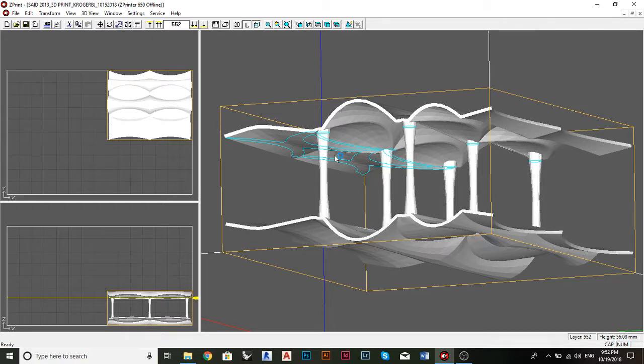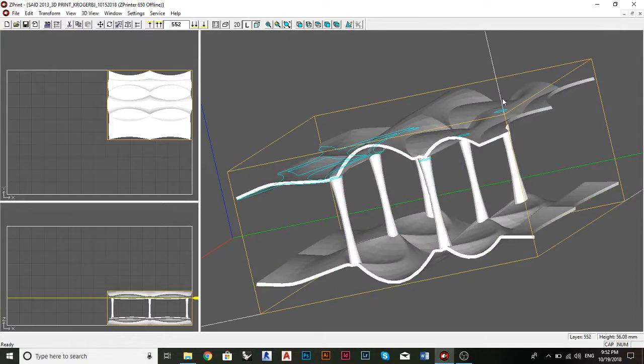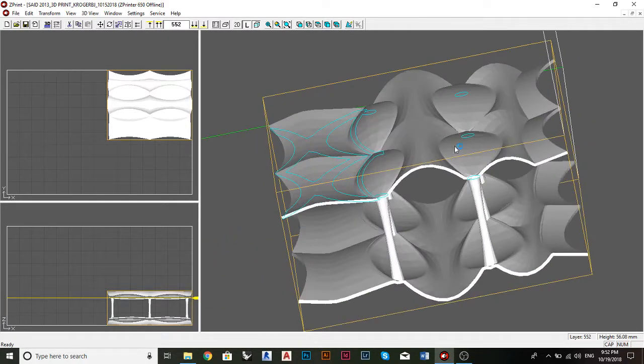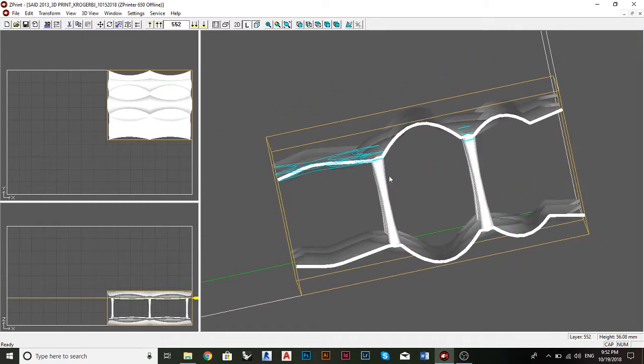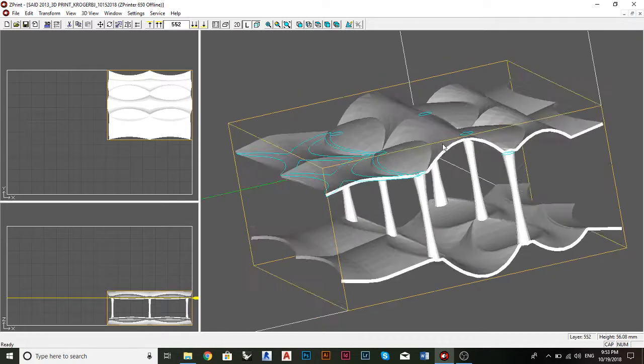Meshes are used a lot for other things, CNCing sometimes, and other 3D modeling software. So you just want to be aware of that. You're more than capable of exporting an STL just from a straight poly surface that is totally closed, has no naked edges, and has no non-manifold edges.